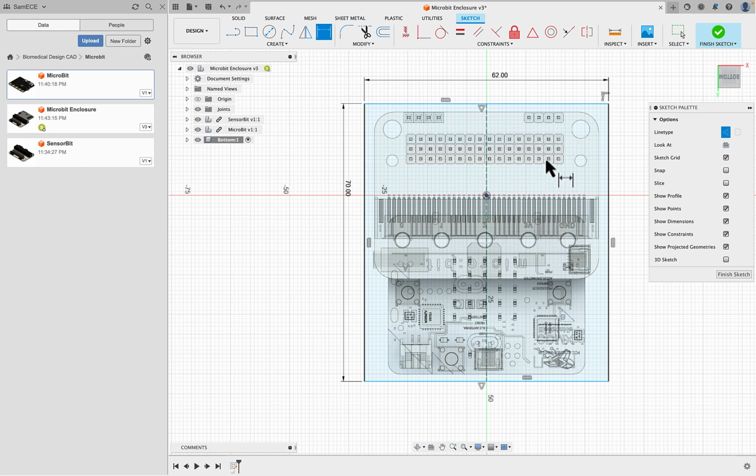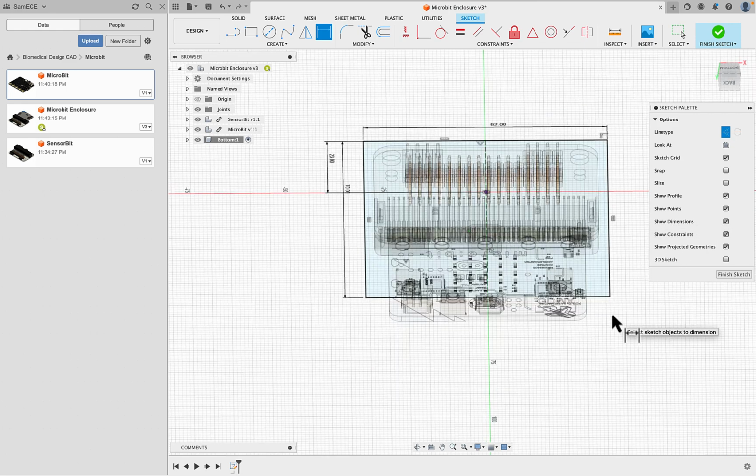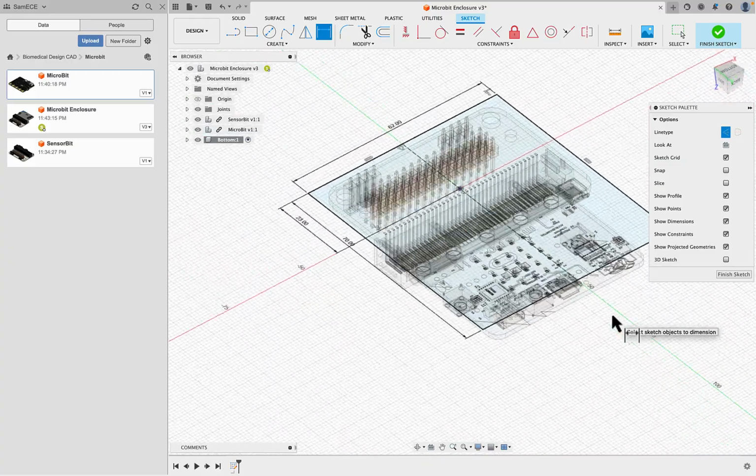So now I've got a design which seems to be centered quite nicely. I would like it to be fully locked. You can notice the blue lines, and that's because I haven't actually set anything in this direction. So I've locked it in this direction because I had the center line going through the origin. So in this case I'll just hit the origin and the top and say, well, I want there to be 23 millimeters between these two, and now it's all black, indicating that I've locked everything into place. So that's a good starting point. Now I have a plane.